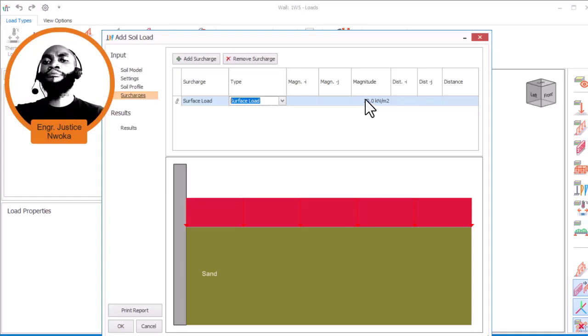Now, the reason why this software chooses 30 is because they have known that the maximum is 20, so they assume that since the code has said the maximum HB load is 20, just to design more safely they increase the load by adding 10 additional, knowing that there is no vehicle load that can reach up to this 30.